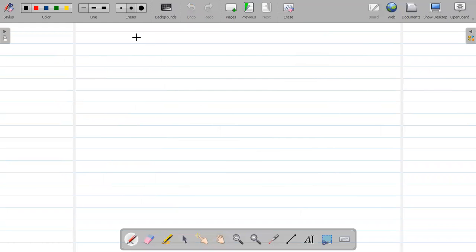We will calculate Ixx2. Let us draw. Ixx2 is equal to ICG2 plus A2H2 square, where H2 is equal to y bar minus y2.